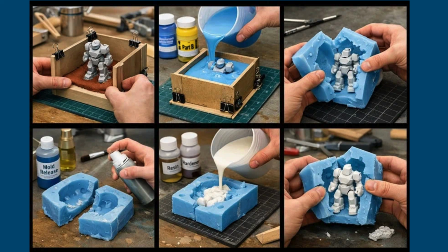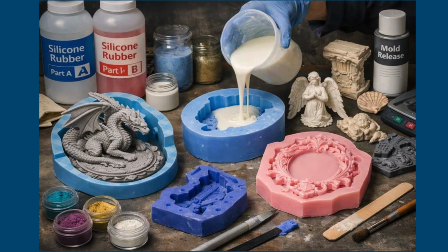Automotive manufacturers use vacuum-cast prototypes to evaluate dashboard components, lighting systems, and interior trim before mass production. Functional engineering prototypes fabricated from polyurethane or composite-filled resins allow mechanical testing, ergonomic evaluation, and assembly verification before investment in steel molds.